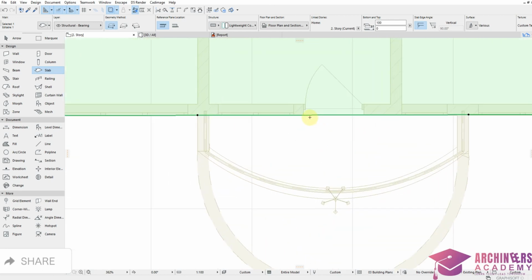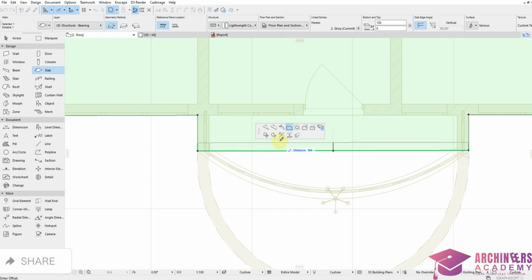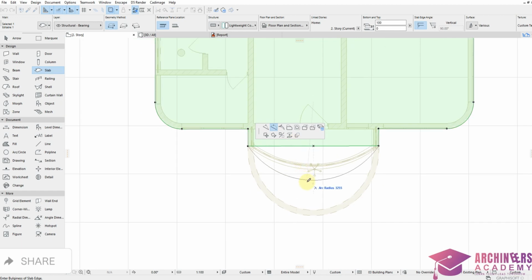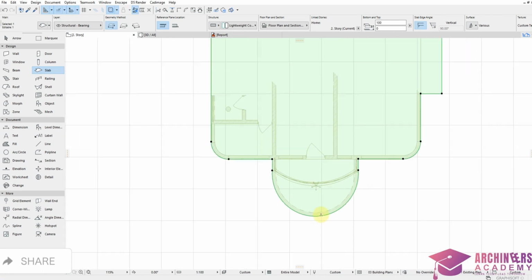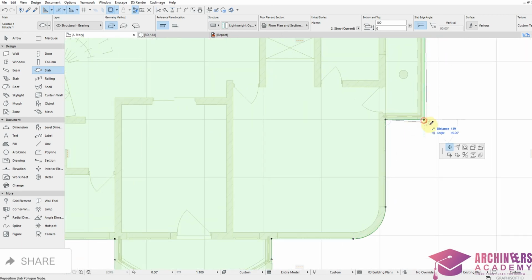So right now we'll extend, since there's a bullet here and there's a bullet here, it can allow us to stretch the concrete fascia only at this part. We're going to use offset edge and bring this part to this front where the straight walls end. Then we'll come to the edge again right here and pick again, then go into curve edge. So you can see it start curving till it gets to that point. So that is done. So right now we can now offset all edges.